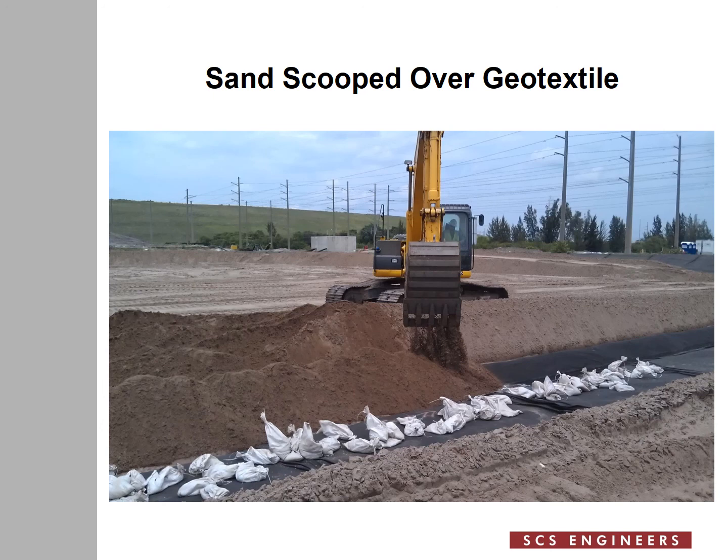That by itself could cause problems in terms of the integrity of the pipe in the long run under the high compressive loads of the waste. And on top of that, the geotextile may get disturbed. That protects the gravel against fine particles from the sand layer.